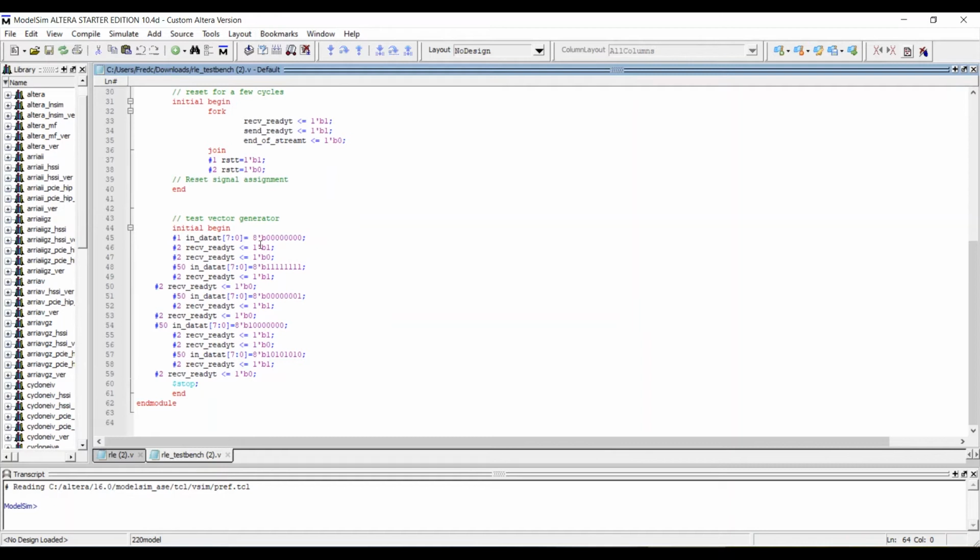Like what I write here, we first did a total 0, and to see if there's a receive test branch from the data master. Then we did another total of 1 to see if this can be sent back. A little bit of change of the code here. Same as what I did here, like the first 7 bits are 0 and the last one is 1, to see if they're coming back. And then there's this test. The first one is 1 and the remaining are 0.